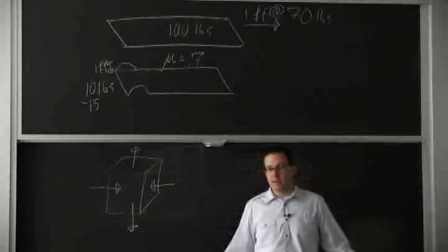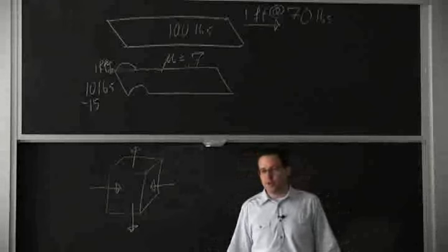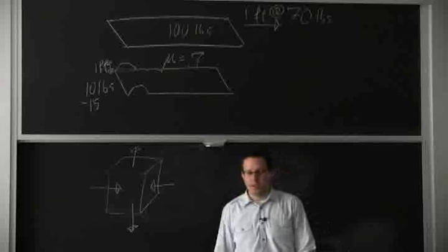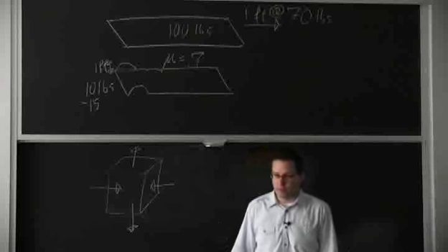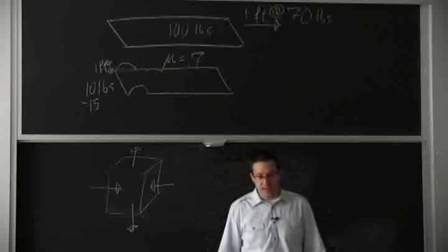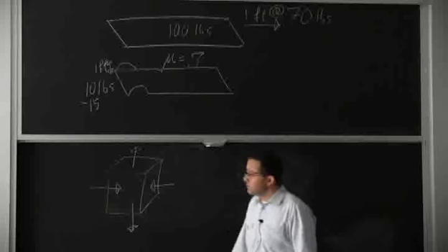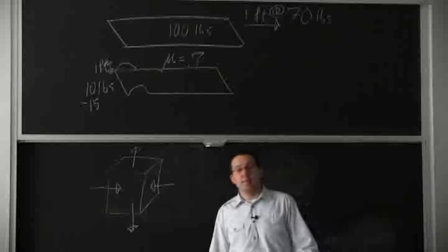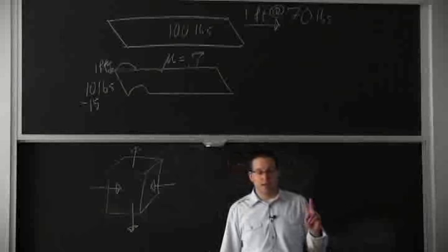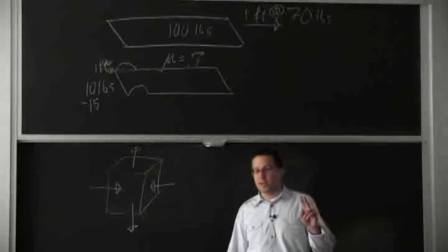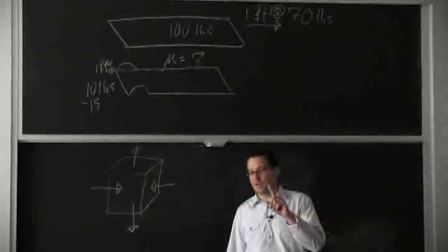that we use it when we don't know exactly the equivalent effect. I mean, we know for a tensile test, yeah, you pull and you have a deformation, and that's how we arrive to these engineering properties. But what if I have tension on both sides? Well, tension on both sides on this schematic brings us here. So we're able to take more stress in two directions before yielding than we are able to take in just one direction.